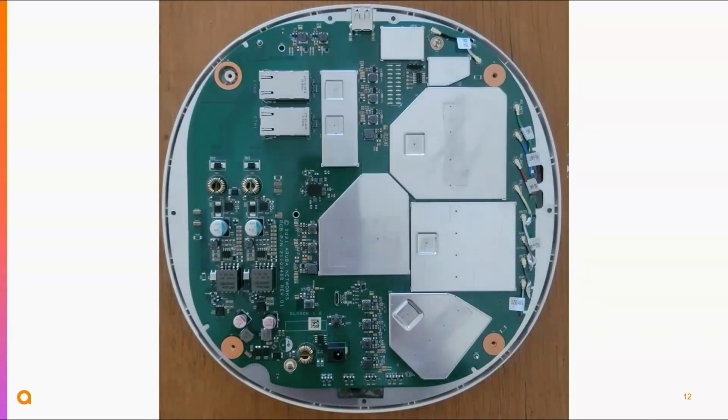Take that out, you see the other side of the printed circuit board with all those components. These are called shielding cans, or the covers of the shielding cans. If you pop those off, which I've done on this sample here, you'll see there's actually a lot of stuff underneath of those cans. And the reason we have those cans is to avoid interference between different parts of the board, and also interference that comes in or goes out to the outside world.